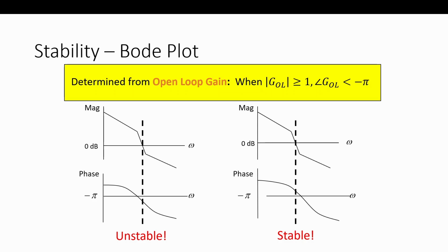So this is the Bode stability criteria. This is a good takeaway. You're going to see us work with that. Ultimately, when this crosses 0 dB, the amount of phase we have from that critical point is called the phase margin.